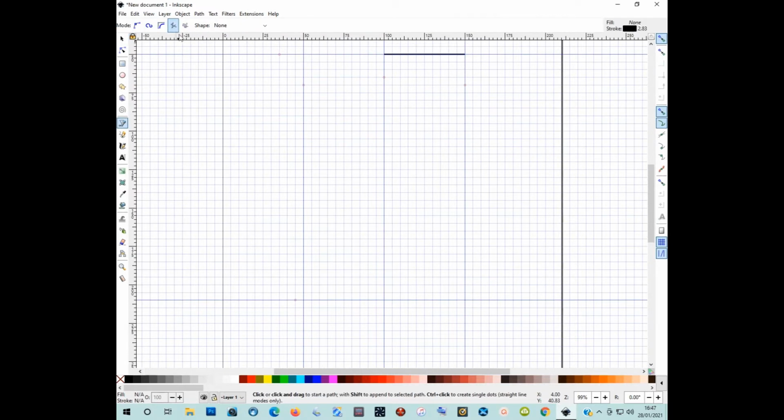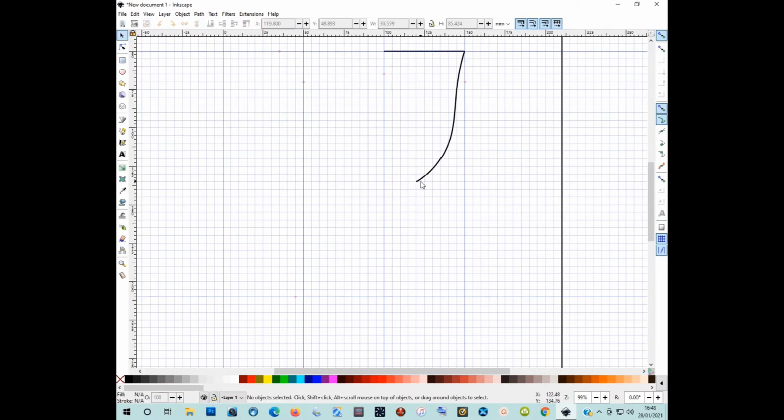Using the curve line option, draw down the bowl of the goblet from the top down to the waistband in a series of steps. Each step creates an adjustment node, which is a reference point which can be modified later. We can fine-tune the shape of the curve using the Node Edit tool to reposition nodes which control the shape of the curve.